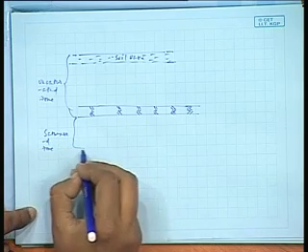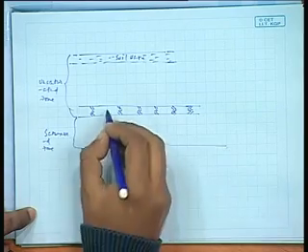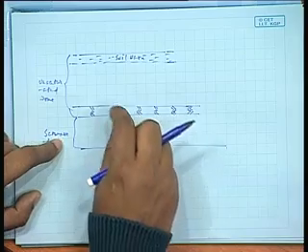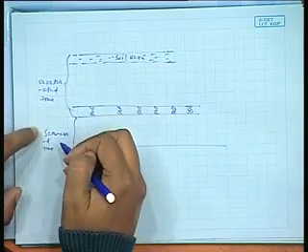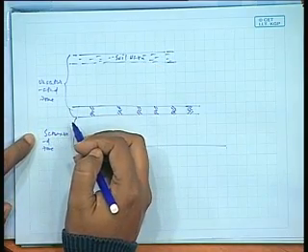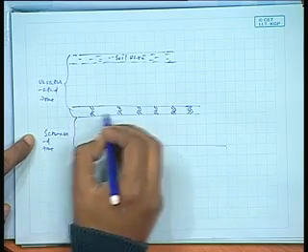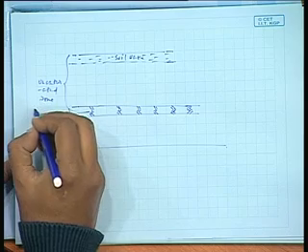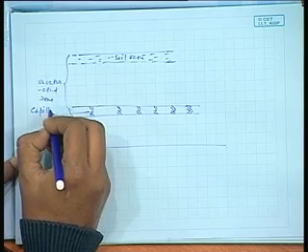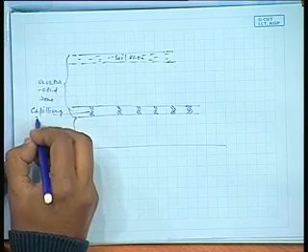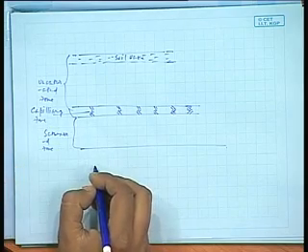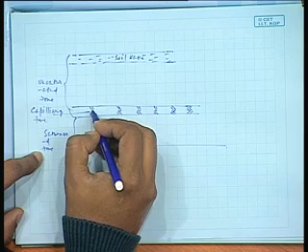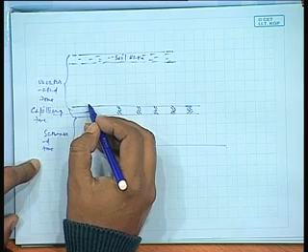Conceptually, there is a zone between them. Is there any line delineating the unsaturated zone and the saturated zone? There is none. In fact, this is basically a capillary zone, where water from the saturated zone continuously moves in capillaries towards the unsaturated zone.